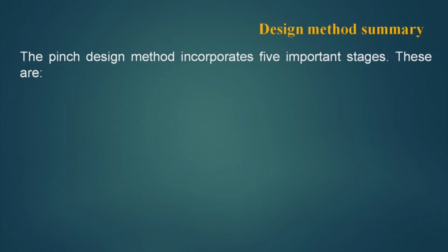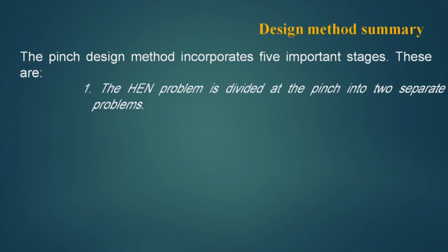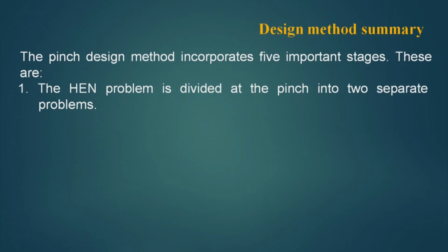The pinch design method incorporates 5 important stages. The stages are: the HEN problem is divided at the pinch into 2 separate problems. This we know because no heat passes through the pinch, and that is why the upper part of the pinch and lower part of the pinch can be made separate, or they can be designed separately, because no heat flows between these two halves.